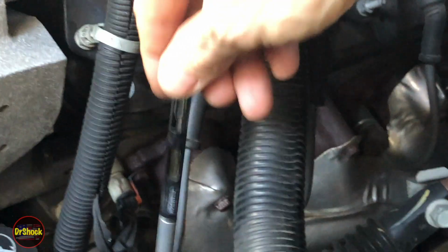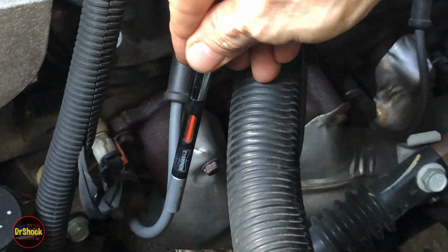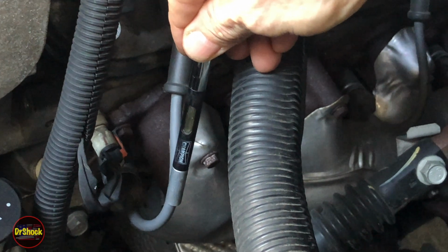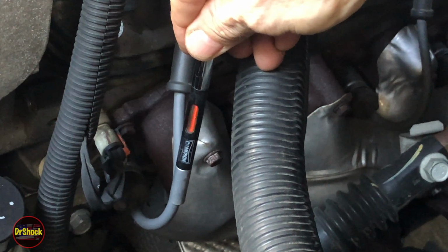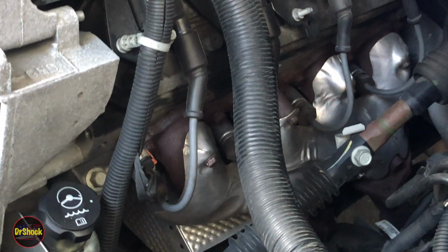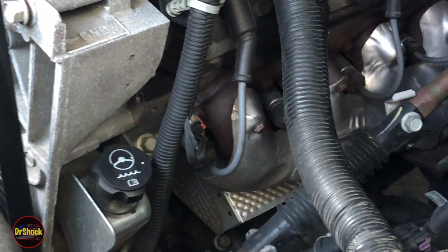Let's do the same thing over here. Right? So we got the same thing going, although you notice it's kind of intermittent. Sometimes it's missing a beat. But that tells me that the coil's not dead. So before we shut the engine off, we just want to do some basic testing like that, because if we had nothing, that might tell us to go straight for looking at the coil.